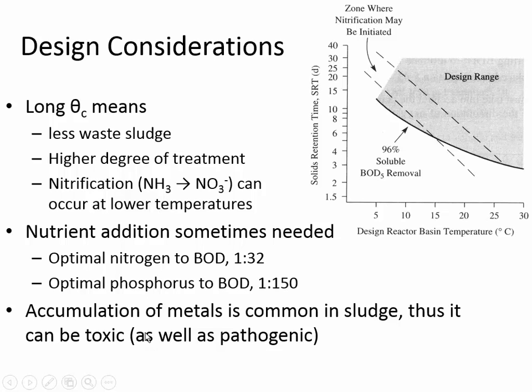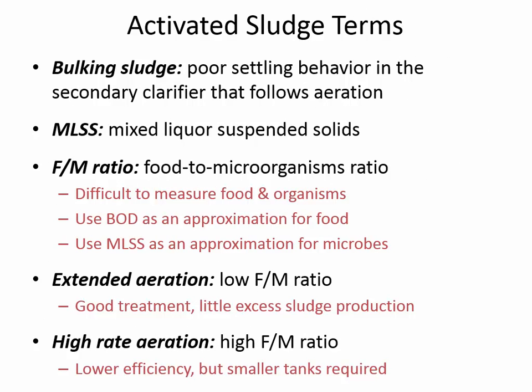And we also have to be aware of that depending on where we put the sludge. Remember, I showed you a picture of a bag of manure that came from the Dubai municipality. They turn their sludge solids into fertilizer. And so that fertilizer, if it had lead or mercury, wouldn't be appropriate for a food crop. Maybe it would be okay to put it on grass, depending on where the grass was and if animals were going to be eating the grass. But you have to do analysis of the sludge to make sure that the heavy metals haven't accumulated in that sludge.